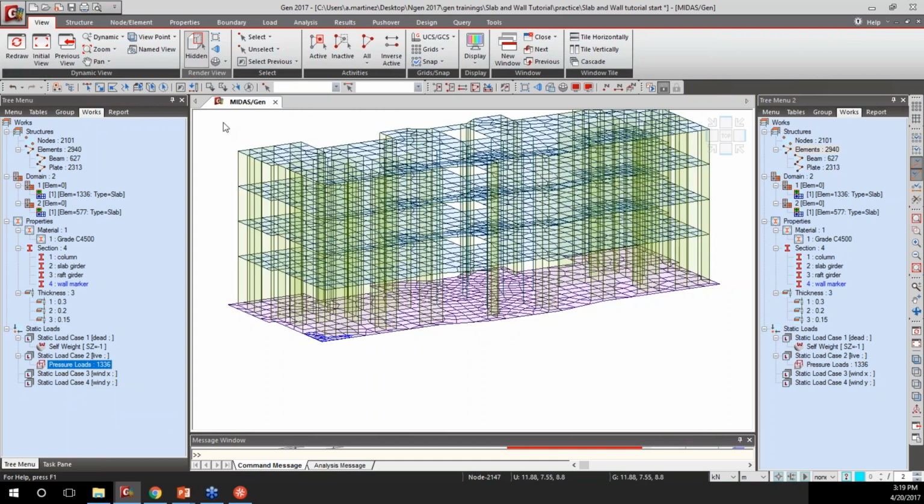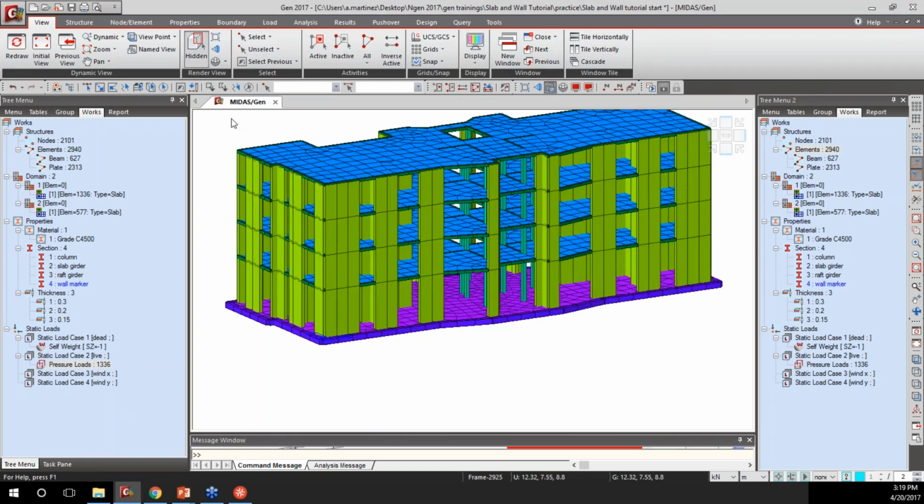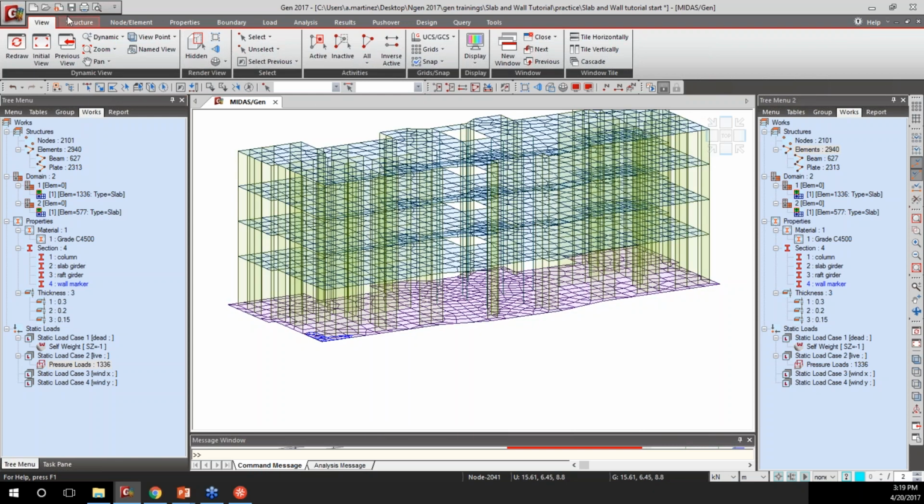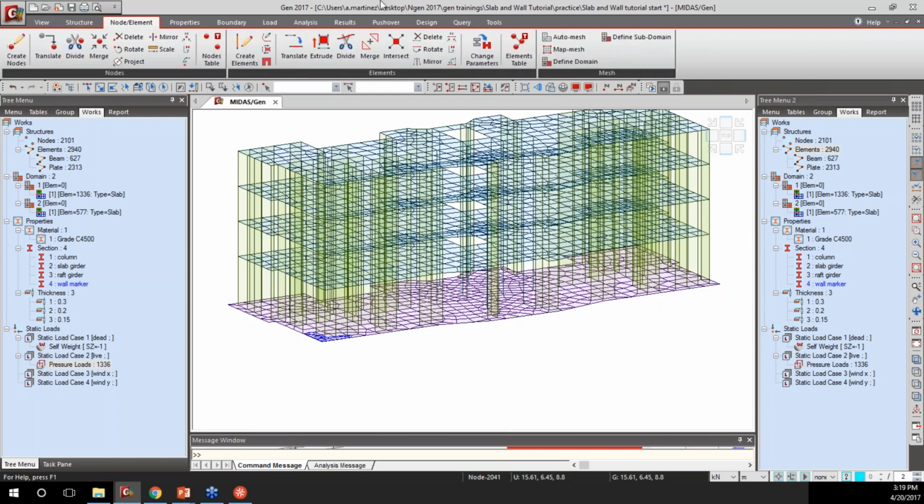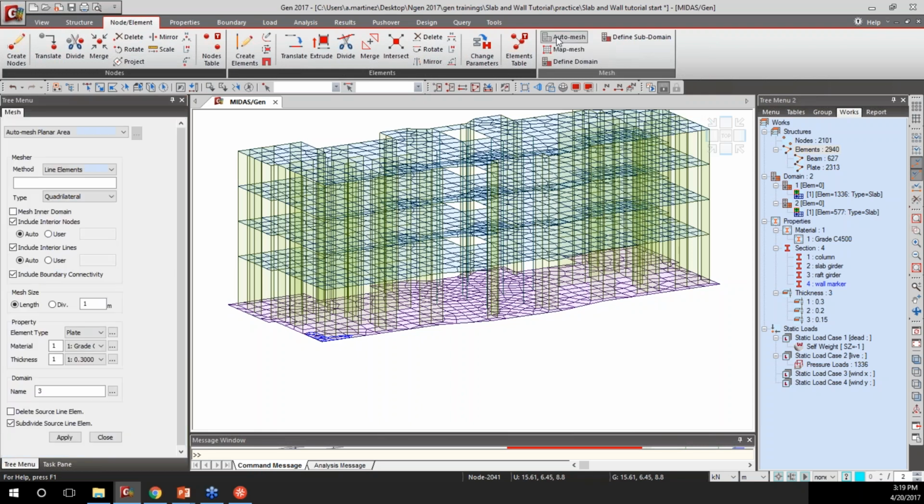Now what we're going to do is mesh the walls. So far we just extruded them, and they're these long planar elements. What we want to do is create meshes that have nodes between them, with a similar distribution and similar sizes as the slab and the wall elements, like a 1x1. You could think of it as remeshing, so I'll use the auto mesh feature again.